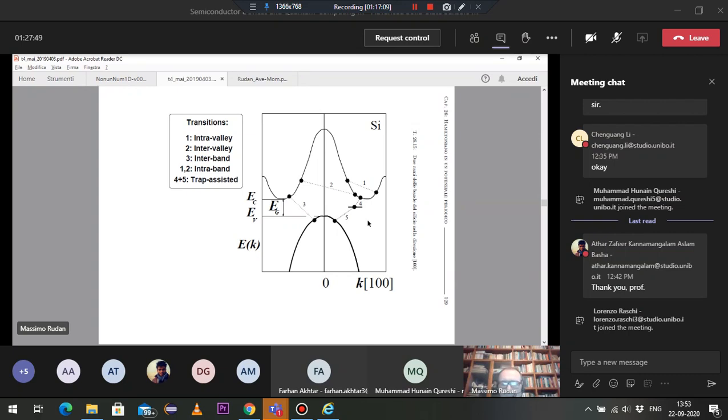If there is this extra energy state, it is also called a trap, because it may be able to trap electrons. It may happen that one electron initially belonging to the conduction band makes a transition of type 4 from the band into the state. If the state is empty, then there is a probability that this state may be occupied by this electron.